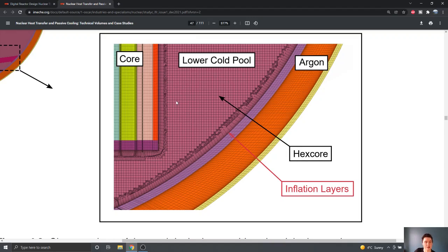All of the cells in the bulk of the pool are perfect cubes of a certain size, and this is really good and really useful for the CFD analysis if you can generate a mesh of this quality, because of course these cells have perfect quality, so they're not going to have large non-orthogonality or skewness, so it's going to be speeding up the solver because these cells have a perfect shape,